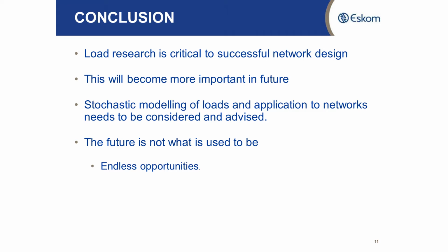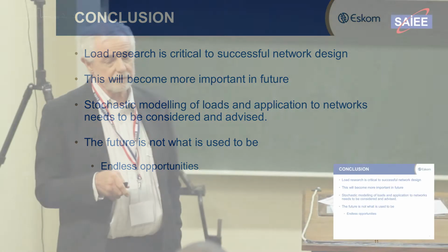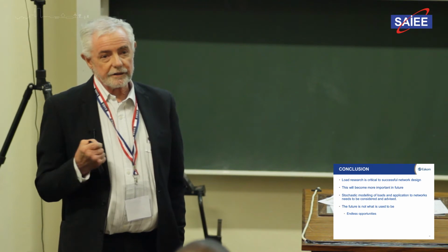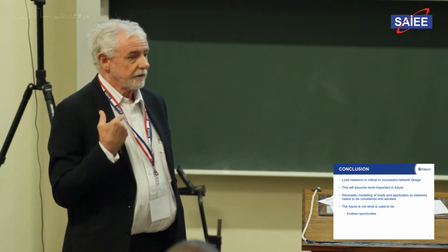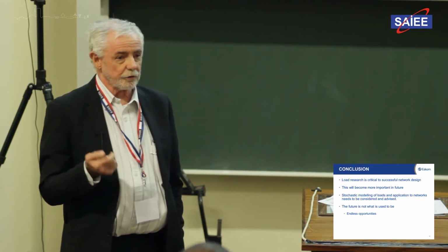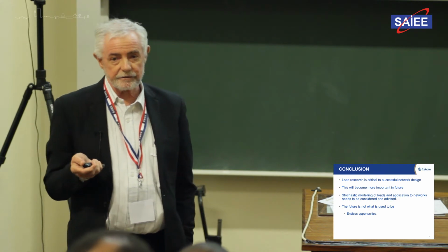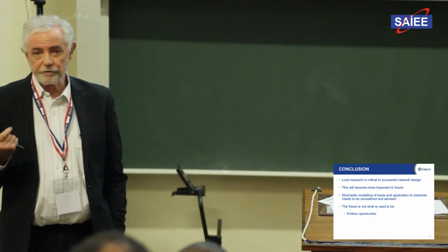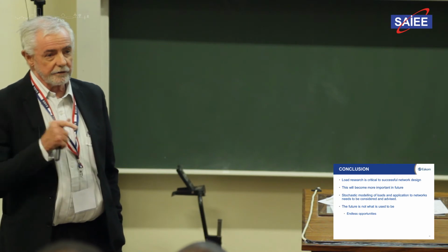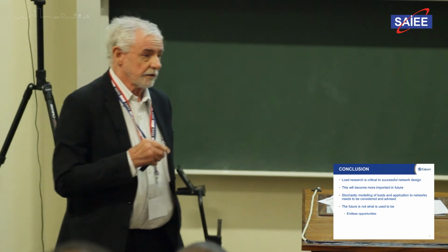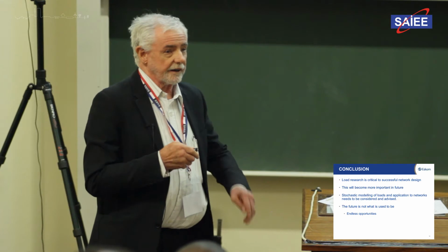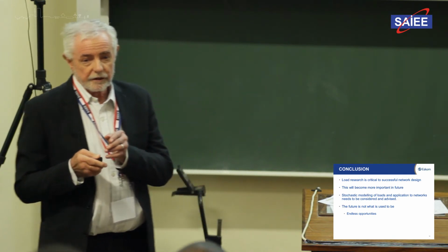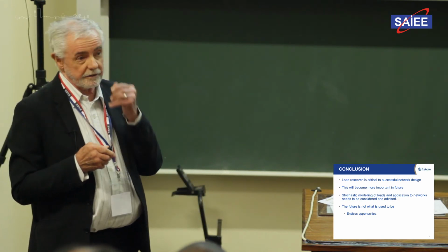The other thing we don't have in this country is markets where you can actually bid onto the grid. What they're doing now, especially in areas like Denmark, is you've got a house with storage, you can bid that as an auxiliary service to support frequency or voltage. And you can do that at any time. So depending on your market design and how the market tariffs work, your load can vary quite substantially.